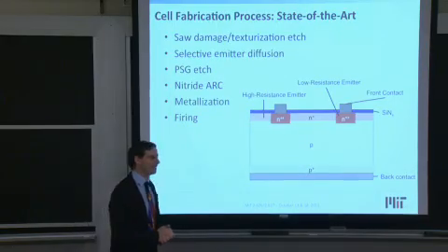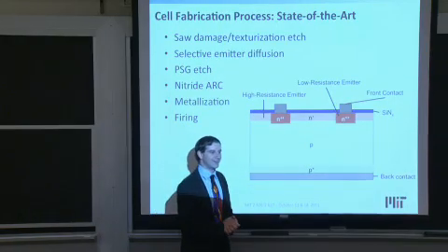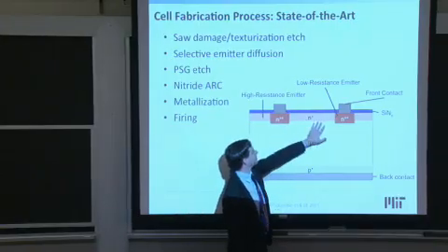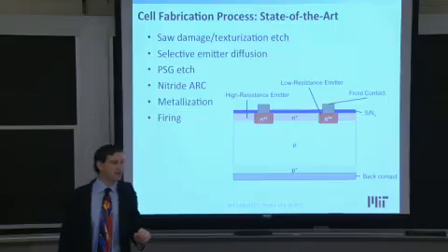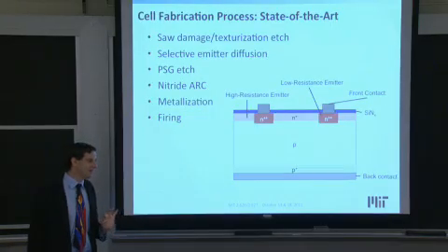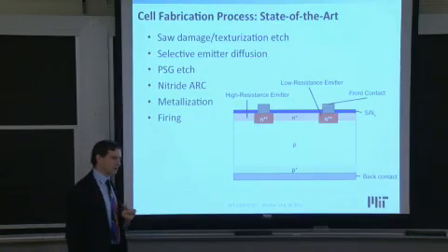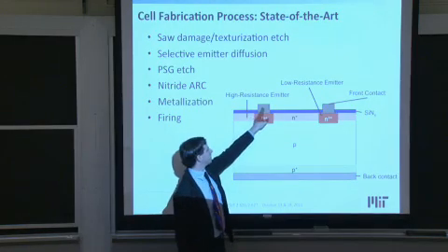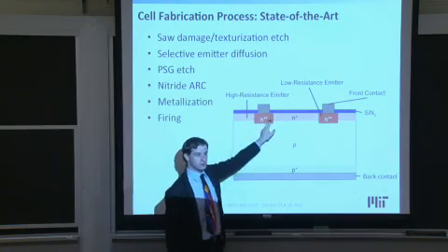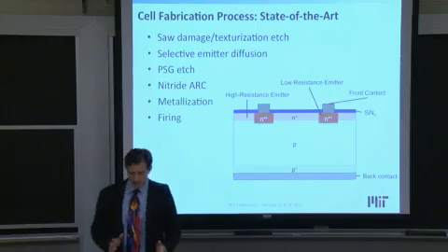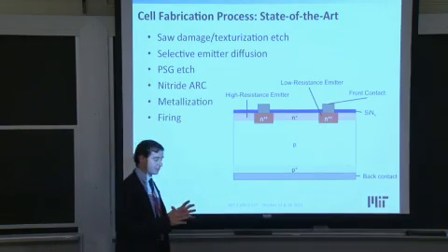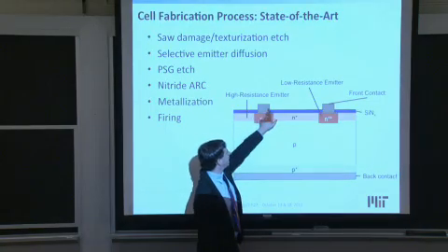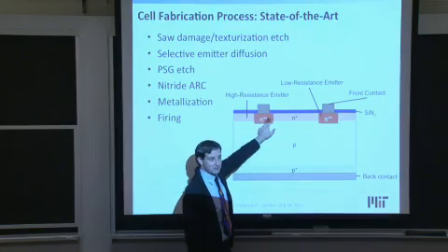So both the front side and back side metallization is aluminum? No, the front side metallization in this case, thank you for the clarification. The front side metallization in this case would be silver or silver-based paste. And in most commercial production, this silver-based paste includes metal oxides. It could be glassy frit, could be lead oxide, it could be some combination of elements that is able to etch through the silicon nitride anti-reflective coating.